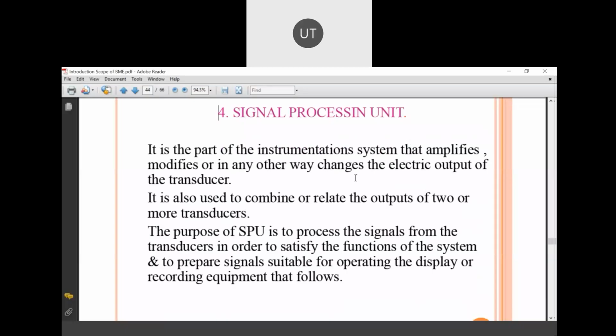Like suppose, for example, the signal we have taken is a combination of the signals of the ECG, EOG, EEG, and EMG. So you must know what the EOG signal is, what the EEG signal is, and what the EMG signal is. If you know that signal exactly, you can subtract it out or filter it out, and you will get only the signal of interest. That is basically whatever signal of interest.